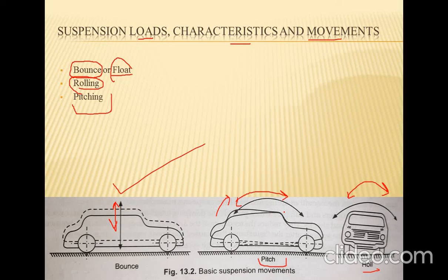This tendency of nose to dip depends upon the position of vehicle center of gravity above the ground, wheelbase and suspension characteristics. Likewise, the torque loads developed during the acceleration lift the vehicle front and dip the rear. The forces caused by braking and acceleration are carried directly by deflecting the springs, by wishbone arm or by radius rods.